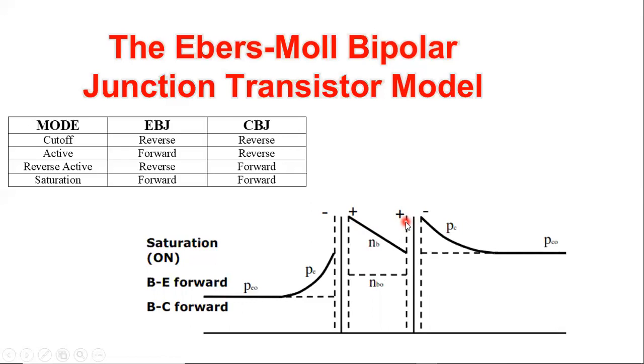But let me answer the first question now. Why are we interested in the minority carrier? We are simply interested in the minority carrier because changes affect only the minority carrier. If you remember from the PN junction lecture, when electrons move from the majority to the minority, the majority will not be affected, but the minority will be affected. So usually in semiconductor devices, minority carriers are the indication for any effect or impact because they can easily be changed. However, the majority are a very huge number, so they will not be affected. So usually we plot the minority carrier, not the majority carrier.